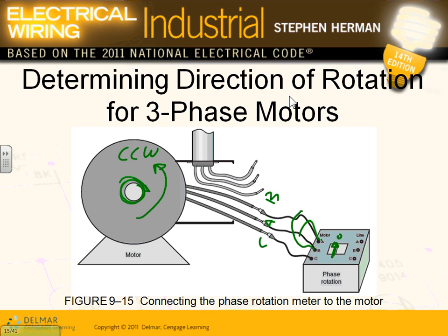Now the question, who cares? You would be a project manager walking into a plant, and they want to add a system, a motor or something, and you have to verify. Ask them for a method. How do you verify the rotation of the motors? So that's a big deal, to verify the rotation of a motor with the phase rotation indicator. Any questions, guys, about this, Chris?